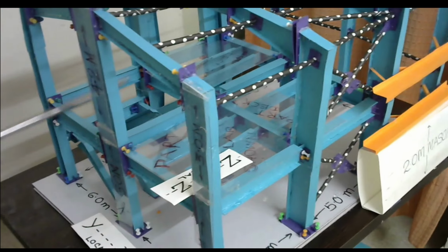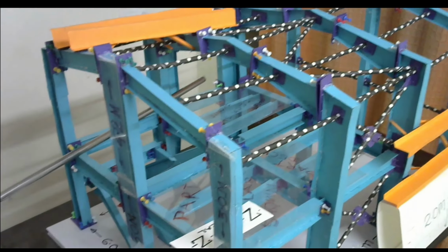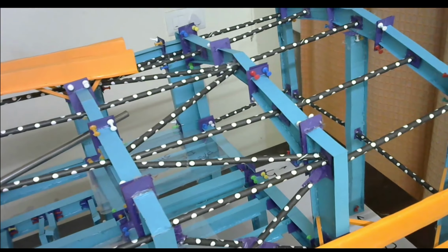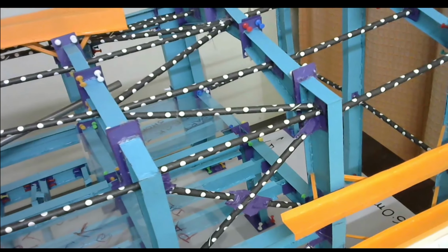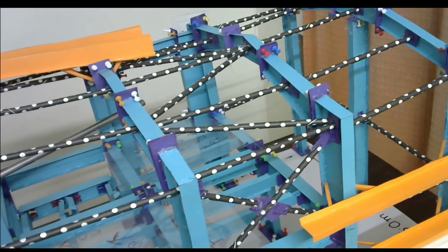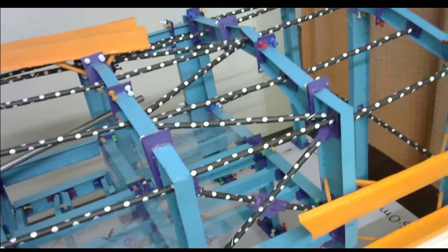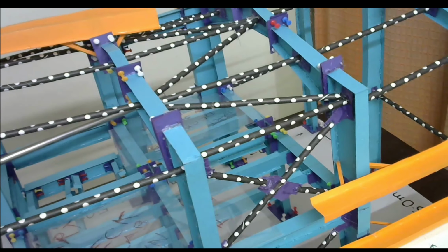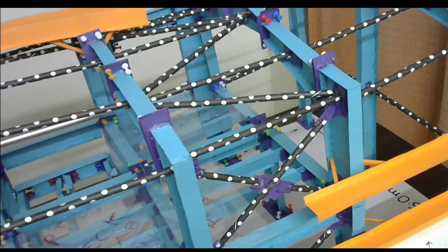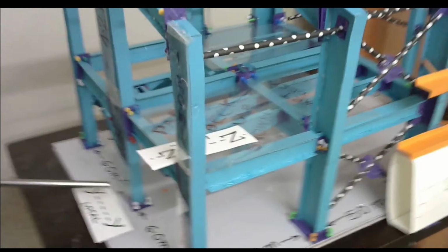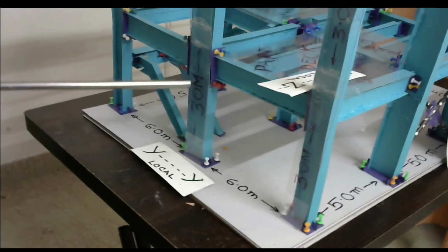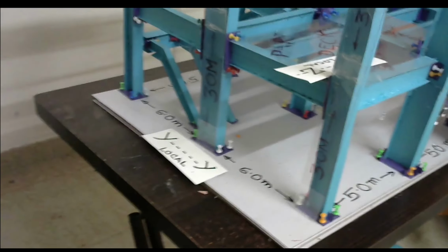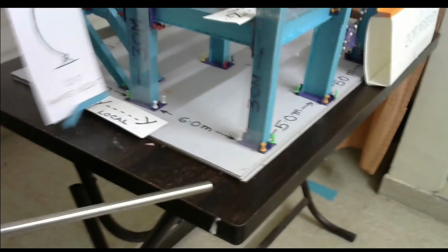About this direction, again if you come to this part as well, there is a portal frame here. The portal frame is a sway frame, but with respect to the portal frame, for all design and practical purposes, we can consider other frames which are extended by this portal as non-sway, provided that there should be a gravity column about that direction. So the effective length of this column also becomes 3 meter, that is 1L. This is our case. YY axis.